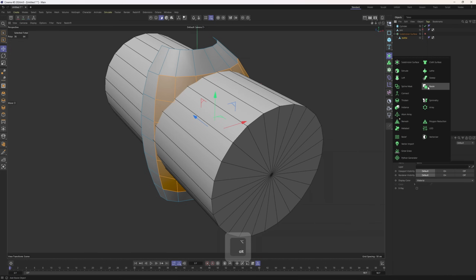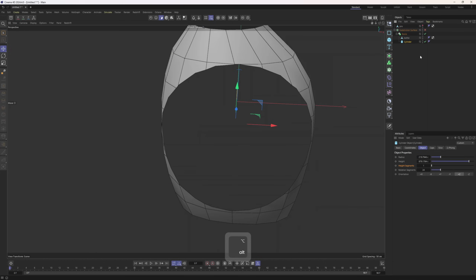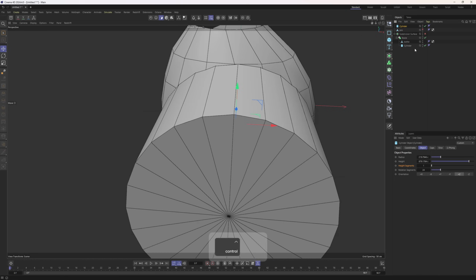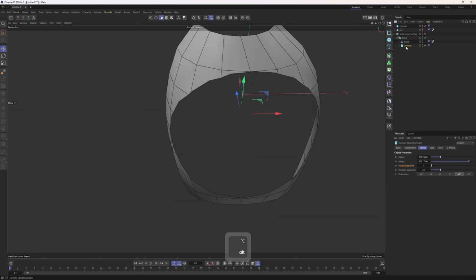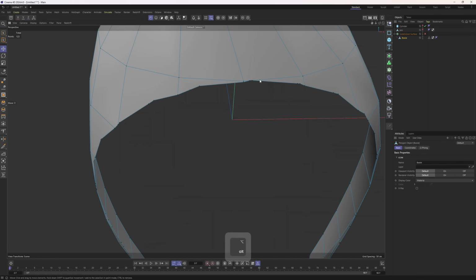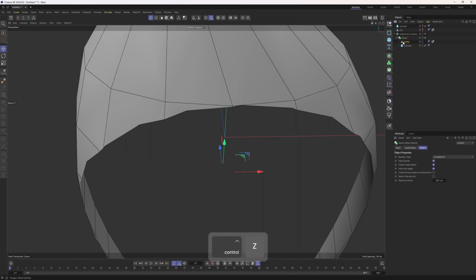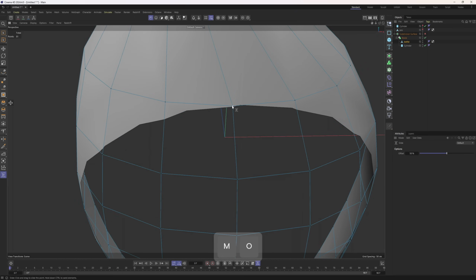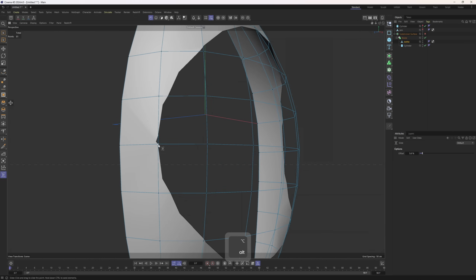And I'm gonna hold down Alt, add in a bool, and put the cylinder under the bottle. I will duplicate this cylinder, Ctrl-C, Ctrl-V. You will see why I did that. Now I will enable create single object and make this bool editable. Actually, I'm gonna step back, and before making this editable, I'm gonna move that point up. Same here. We don't want this to overlap.